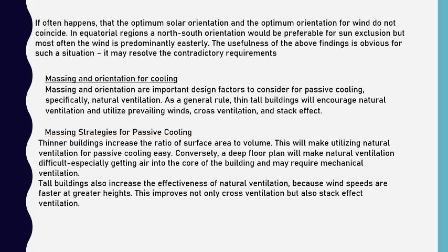First is massing and orientation for cooling. Massing and orientation are important design factors to consider for passive cooling, specifically natural ventilation. As a general rule, a thin tall building will encourage natural ventilation and utilize prevailing winds, cross ventilation and stack effect.